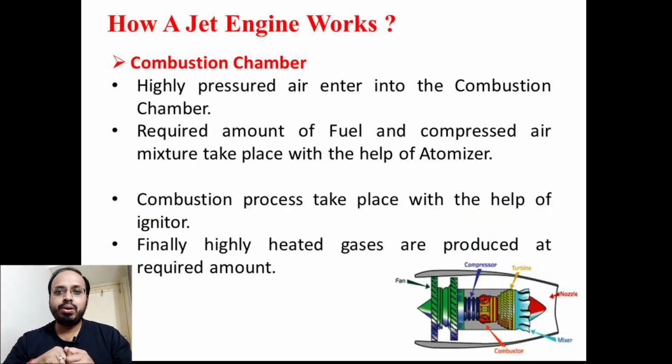The third component of the jet engine is the combustion chamber. The highly pressurized air enters into the combustion chamber. The required amount of fuel and compressed air mixture takes place inside the combustion chamber with the help of an atomizer. The atomizer is one of the components doing the mixing. And then this mixture is ignited with the help of an igniter and the combustion process takes place.